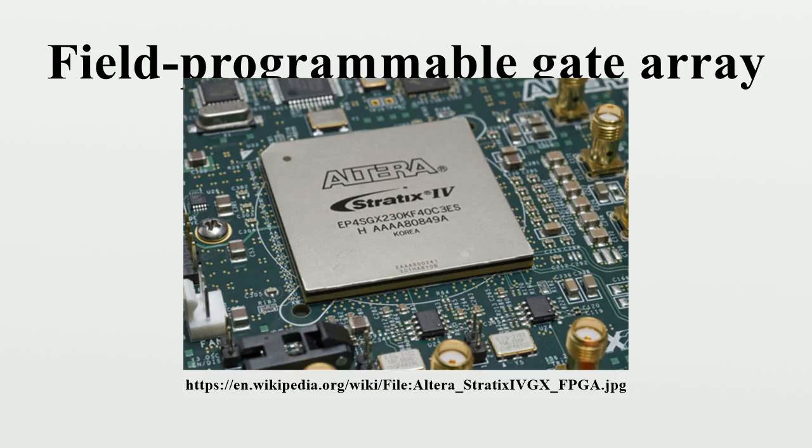Security considerations. With respect to security, FPGAs have both advantages and disadvantages as compared to ASICs or secure microprocessors. FPGA's flexibility makes malicious modifications during fabrication a lower risk. Previously, for many FPGAs, the design bit stream was exposed while the FPGA loads it from external memory. All major FPGA vendors now offer a spectrum of security solutions to designers such as bitstream encryption and authentication. For example, Altera and Xilinx offer AES encryption for bit streams stored in an external flash memory.